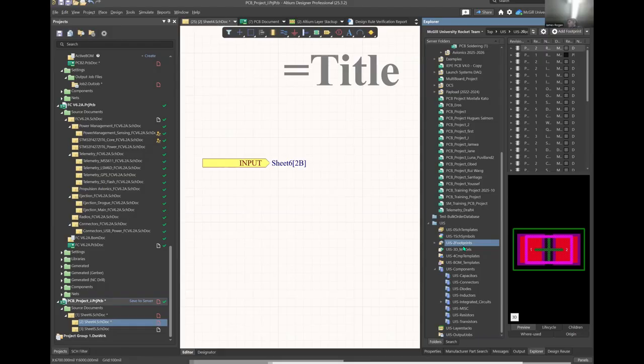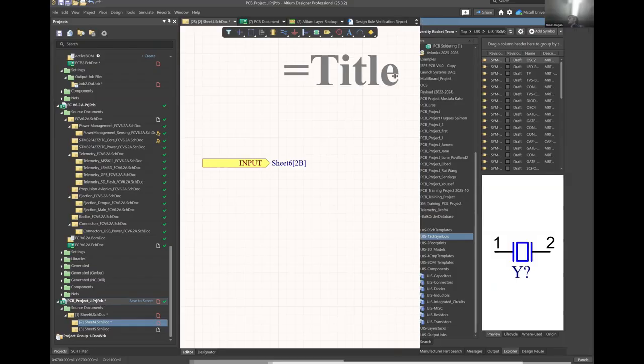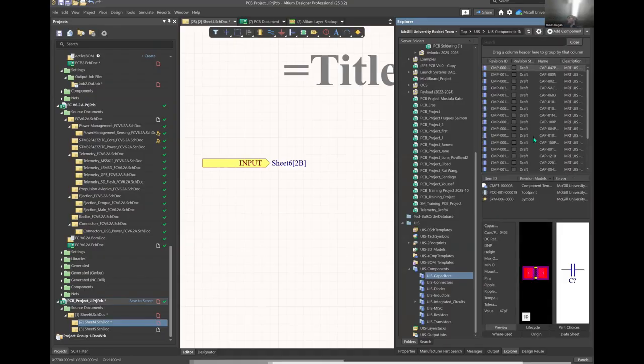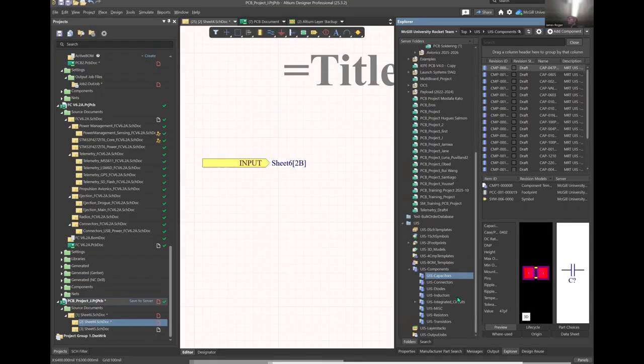If you wanted to reuse the design from one project in another project, you would have to make sure the dependencies for the footprints and the symbols are available so that they can be linked. That means having all of these files available. With this, it automatically links them for every single component that's placed in every single file that's on the cloud here. It automatically resolves the dependency. Does that make sense?